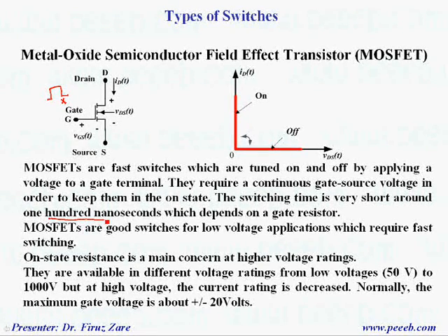And the point is that when a MOSFET is on, the conduction loss depends on the on-resistance. That's why at high voltage this resistance gets high, so it's not a suitable switch for very high voltage applications because the total loss will be high.